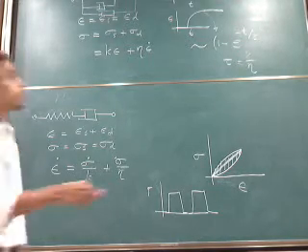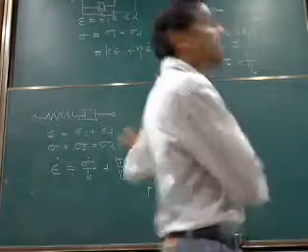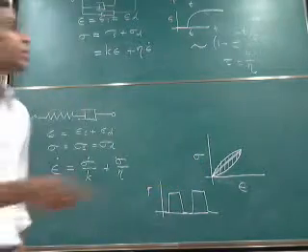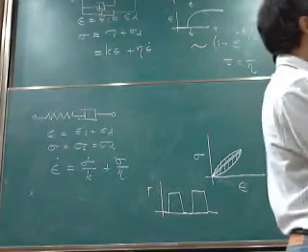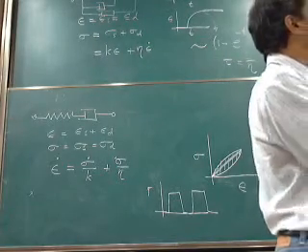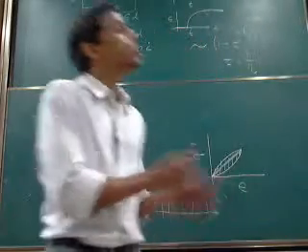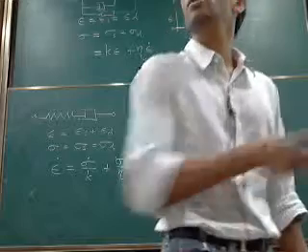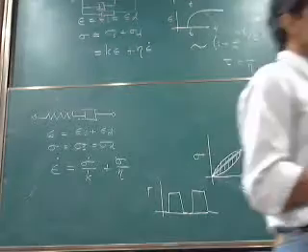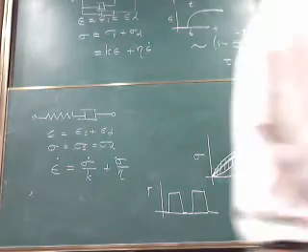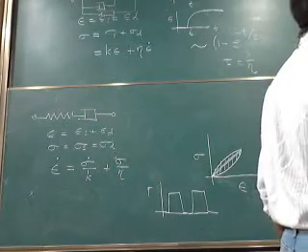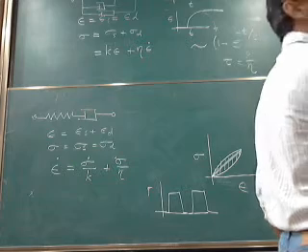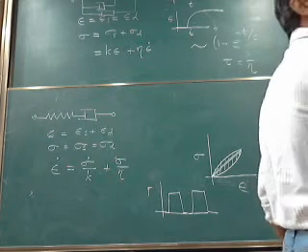So from this experiment, again from considerations like what I described earlier, they conclude that this material is made of a combination of springs and dashpot like that. This can be modeled by this sort of a system. Why not only viscous drag is responsible? If it is only viscous drag, I rubbed it off earlier, you will not see this. You will see only this part.